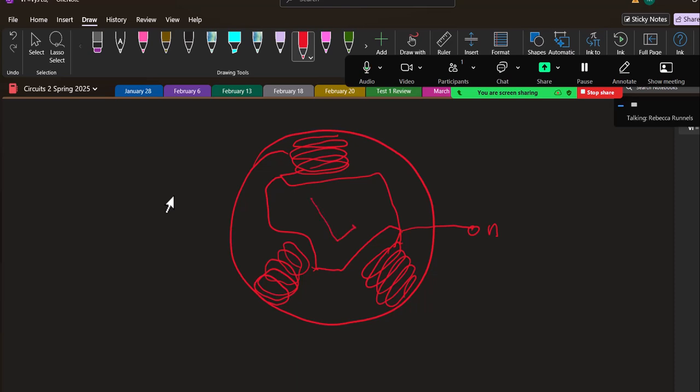And then here's my magnet, and it's going to spin with some angular rotation, omega, probably a frequency of 60 hertz. If I am measuring a Y voltage, then I'm measuring the voltage of this coil relative to this neutral. If I'm measuring a delta, I'm measuring the voltage of this coil relative to that coil.